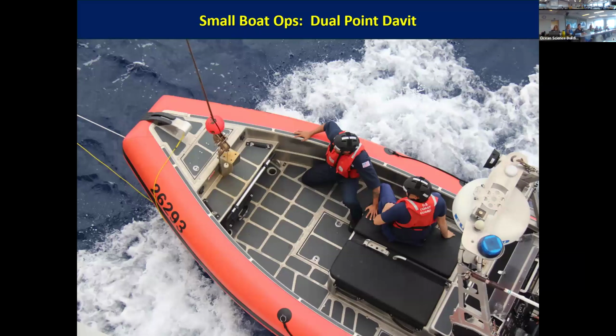You got the 2 points to the davit, but there is a line off the bow that leads up forward. We are essentially dragging the boat alongside the ship. We will disconnect the davit, and we're still towing it alongside. And then a crew member up forward is going to have to go and release everything. That's a hard job to do if the boat is pitching around.